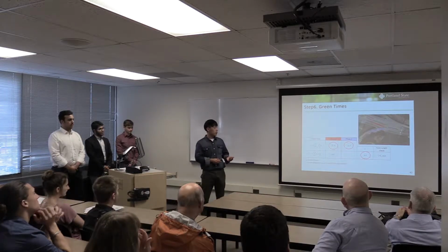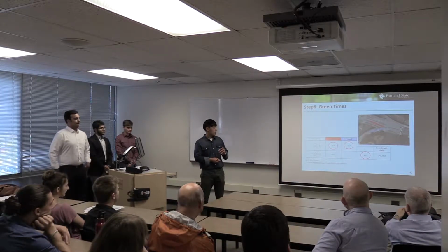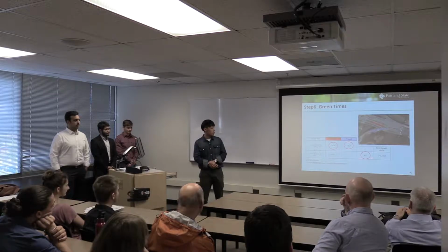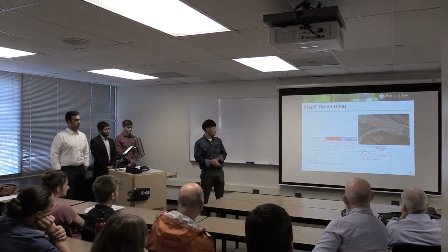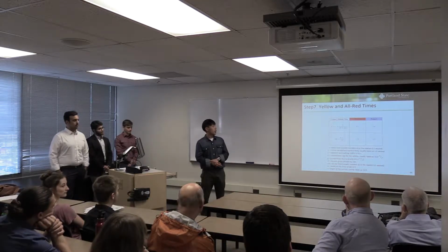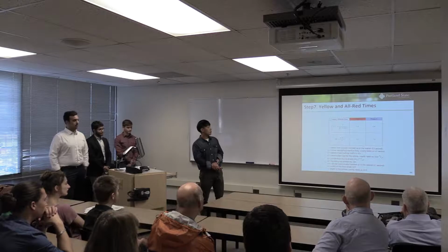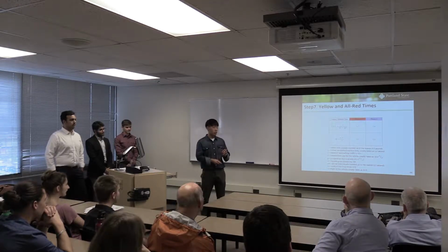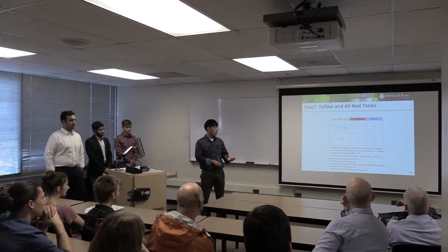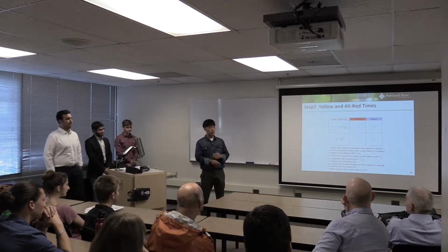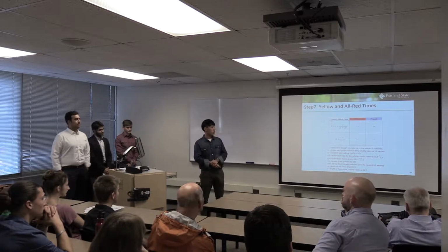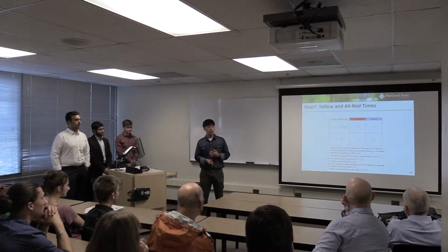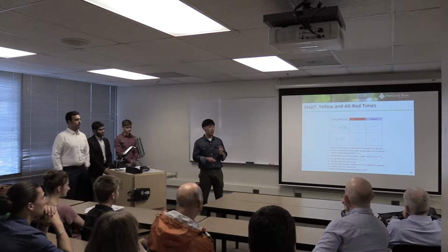So we were able to verify our number is okay because green time for both phases, summation of those and then total lost time matches with our cycle length. After that, we calculated our yellow and red time. For this calculation, we used a lot of human factors, for example, driver's reaction time, speed of vehicle, deceleration or acceleration, percent grade, divided by 100. For those numbers, we only used standard numbers to get the standard signal timing.